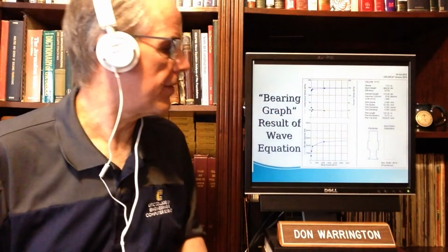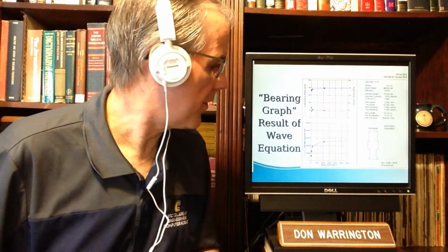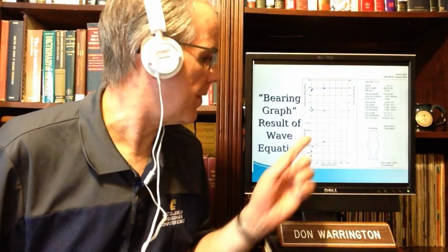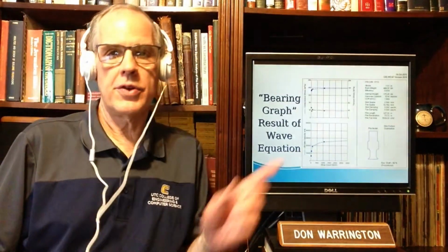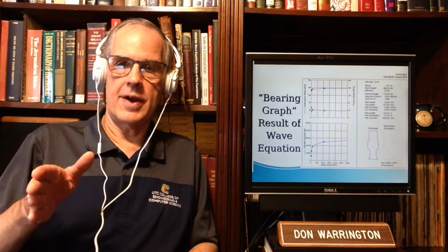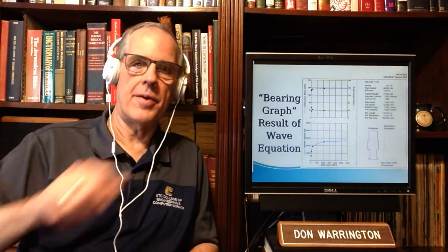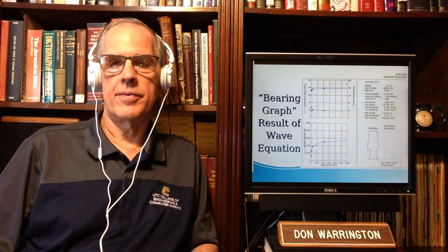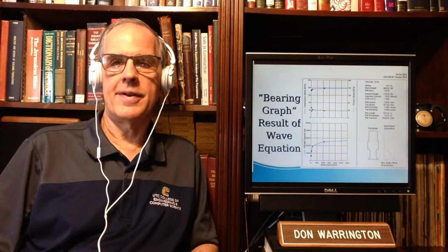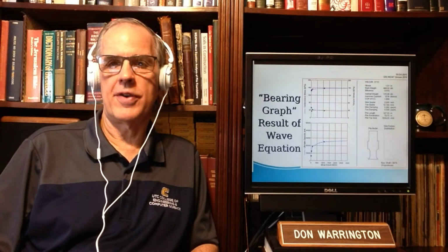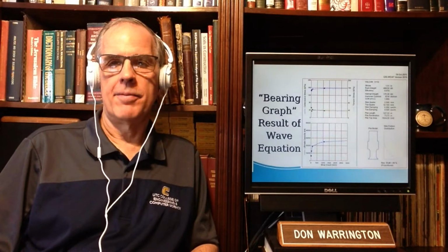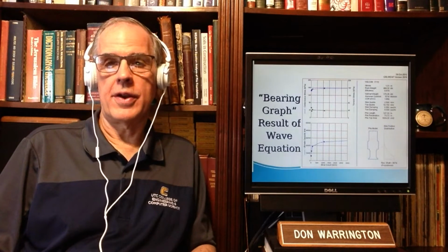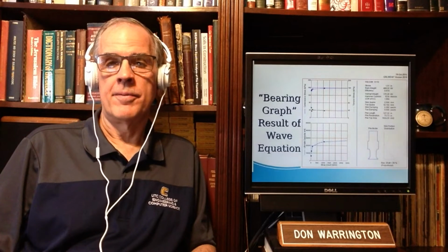There are three things that you get out of this. The first is the blow count versus the ultimate capacity, the one at the bottom. You'll notice in this case that it comes up and then it flattens out. Obviously, you reach a point where just beating on the pile you get a diminishing returns effect, where it just doesn't do any good. In addition, it damages the hammer and the pile.